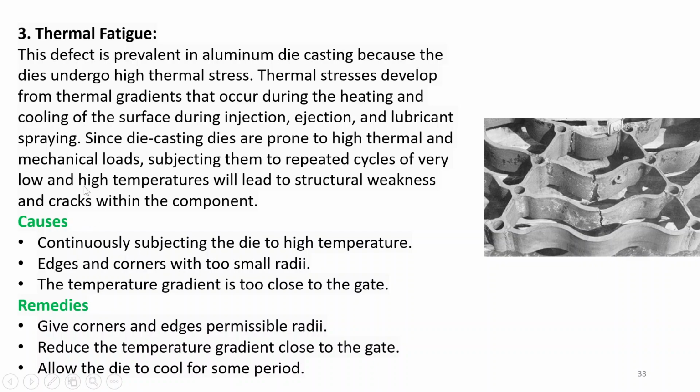Now the causes of thermal fatigue are continuously subjecting the die to high temperature, edges and corners with too small a radius, and also the temperature gradient being too close to the gate. Now this can be prevented by giving corners and edges a permissible radius, reducing the temperature gradient close to the gate, and also allowing the die to cool for some period.